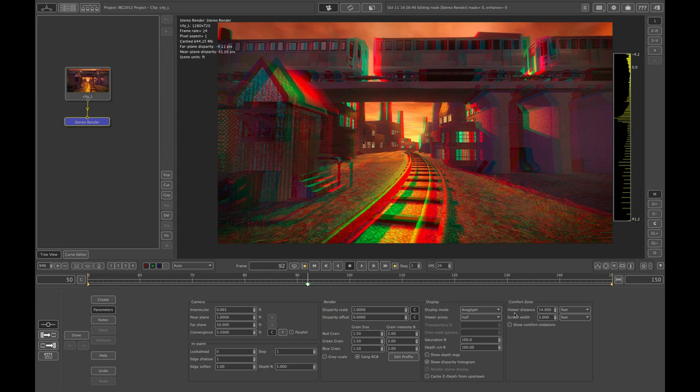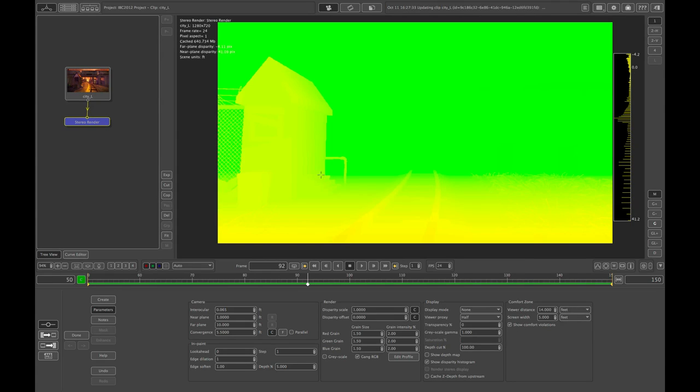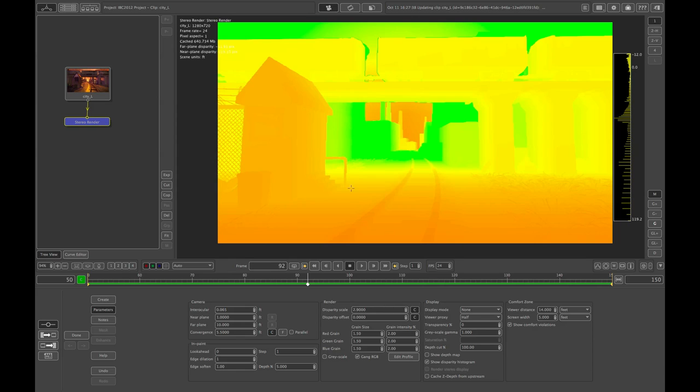This is based on some basic viewing conditions that we've set up, and everything in PFDepth is based on the human condition. So if I turn this on, it's based on a simple red, green, and yellow stoplight kind of warning system, where anything that's sort of red is in danger of causing comfort zone violations in the form of things like eye strain and motion sickness, and as we progress back into green, everything becomes a little bit more safe. So what I can do is use this to give me a lot of valuable feedback before I've even rendered out the image to tell me if there are going to be any potential problems.